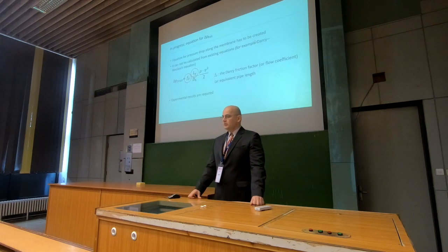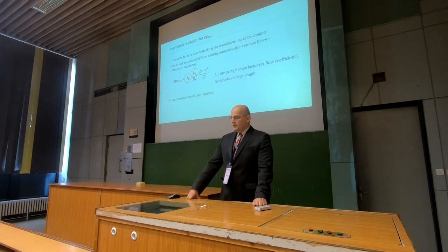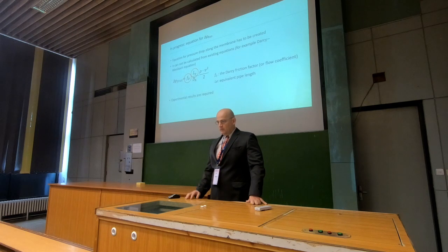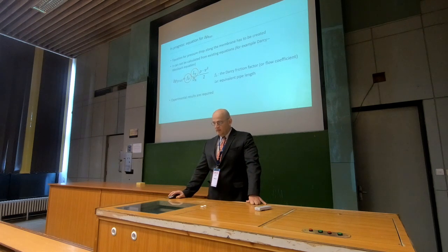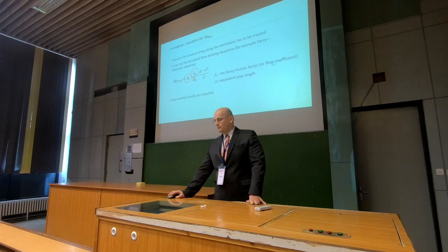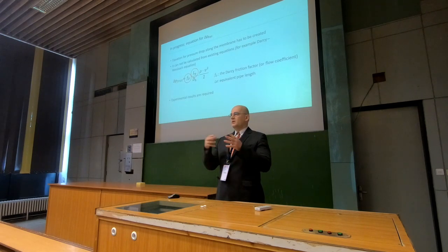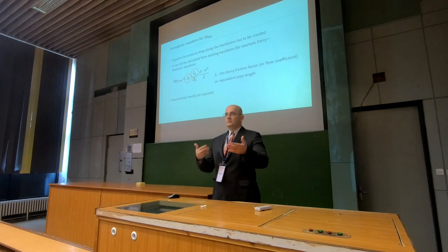And the pressure drop along the membrane. An equation for the pressure drop along the membrane has to be created, but we cannot use the existing equations, for example the Darcy-Weisbach equation, because we have two unknown variables inside. We don't know the friction factor or flow coefficient between the fluid and the membrane, or the fluid and the material of the static mixer, and we have two different materials here.